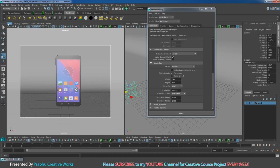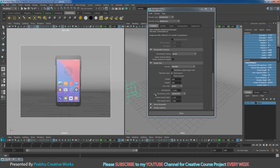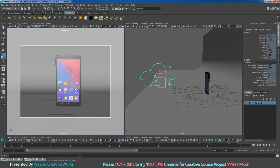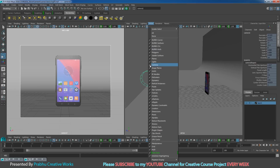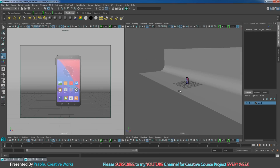Now go to view and choose select camera. I will select all my camera values over here, right click and choose lock selected. That means you cannot move the camera view. Now I want to hide my camera shape in perspective. Go to show and disable the camera. That means it will not show in the perspective view.